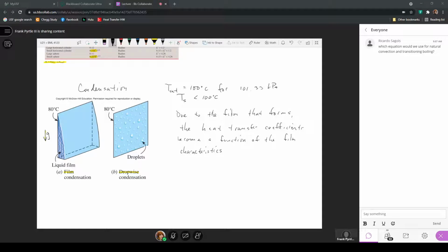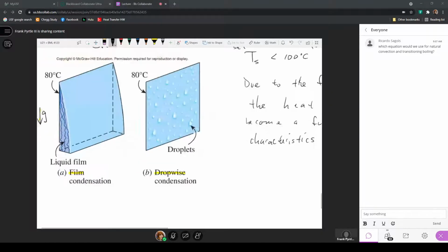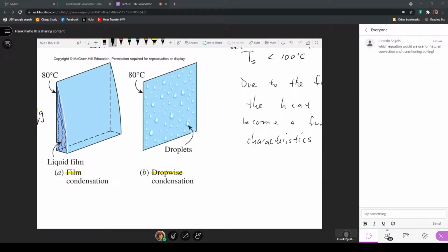And in your text, they talk about flow regimes for this film, such that they're defined as wave-free and wavy. A wavy one is like the velocity distribution that's drawn here in the thickness in these darker blue lines. That would be a wavy film, and it's typically considered to be laminar, and there's a turbulent condition for fluid that is essentially falling off of the surface.